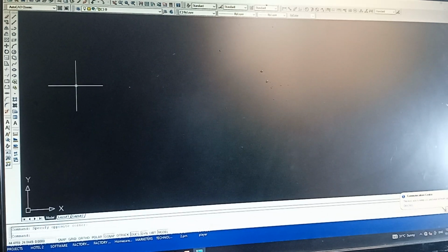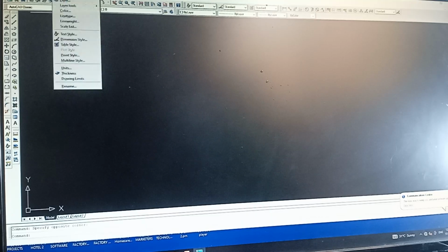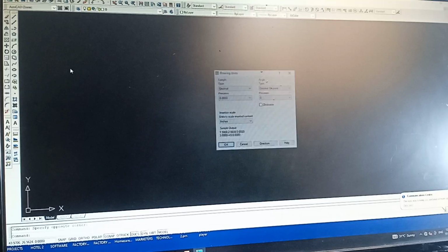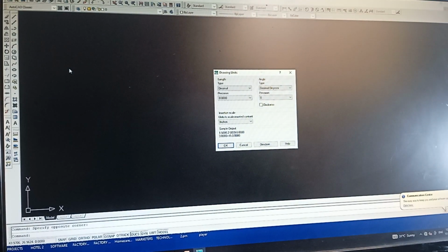Then in setting working environment, there is a particular place we'll go to. It is called format. This is under your command bar. So we click our format to set our working environment. So I click format, and then under format the first thing we need to set is we go to our unit. What kind of unit drawing are we doing? We are using universal decimal drawing.